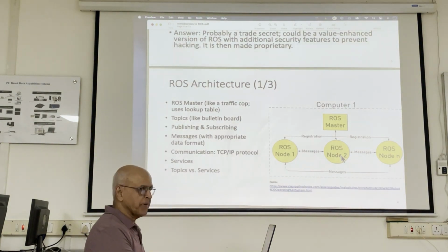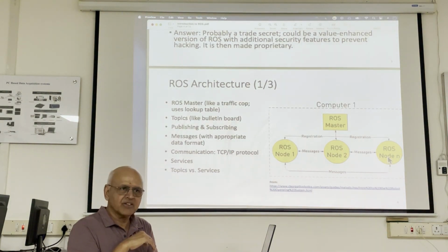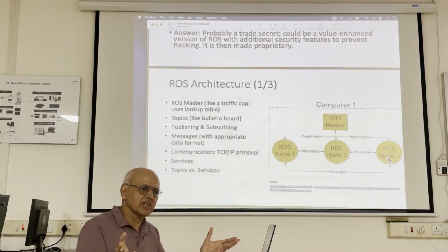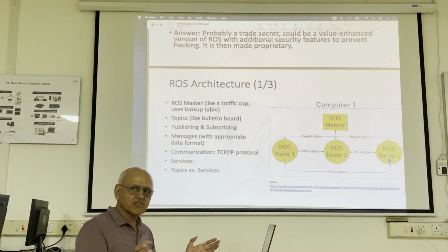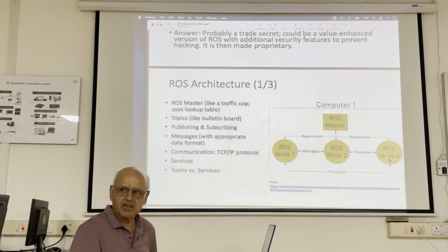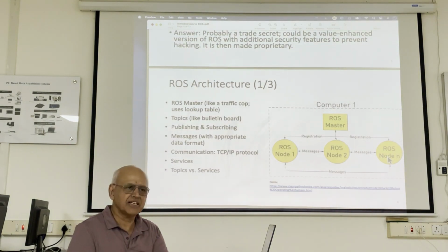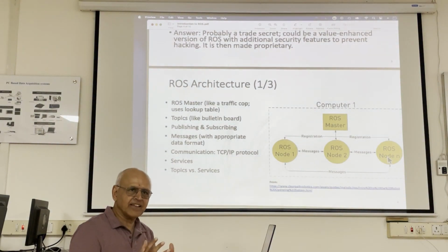Here's an example of topics, right? We kind of flew through this the other day. So we have 3 nodes, and we don't know what their functionality is, but by now you know enough. There could be an image processing node, there could be 2 image processing nodes, maybe you have 2 cameras on a robot. Imagine if you have 10 robots doing patrol and each one of them has 2 cameras, the number of topics multiplies quite a bit. There might be somebody sitting in a central monitoring station, wanting to see what the robots are seeing, or maybe do some higher level processing of those images, some artificial intelligence based processing. So topics is the way that you get access to those different pieces of data.